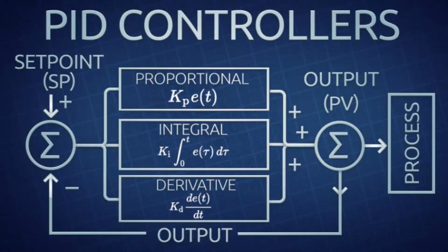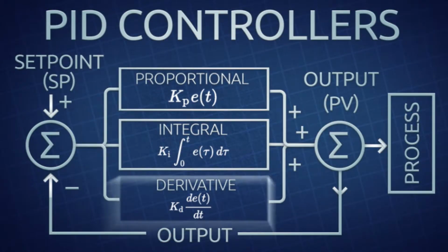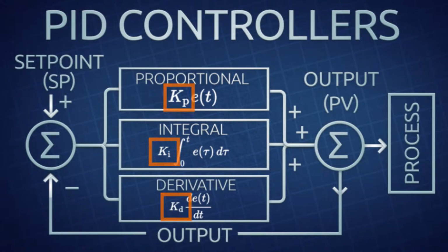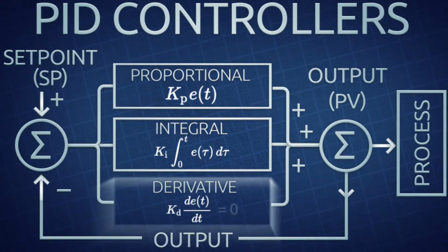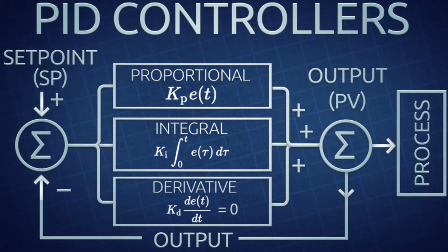A PID controller consists of 3 terms: proportional, integral and derivative, which are tuned by 3 non-negative gain parameters. The values of all terms are then summed and produce an output value. There are more variations of PID controllers created by a selective use of control terms. For example, the popular PI controller, which has the KD gain set to 0, is less sensitive to measurement noise.